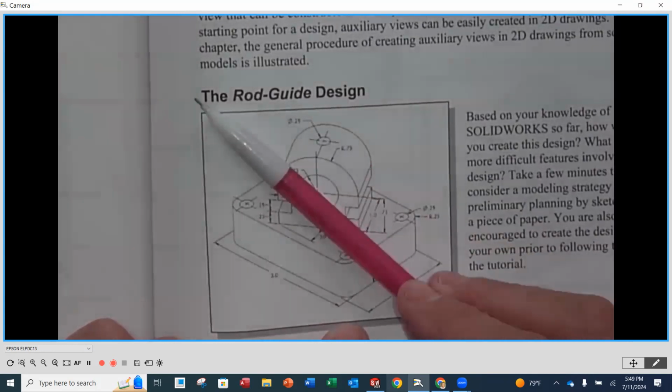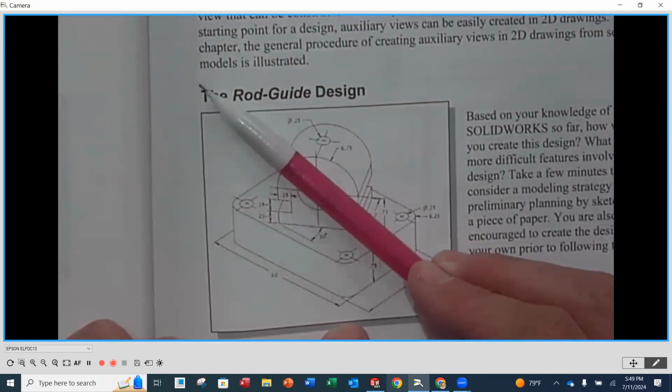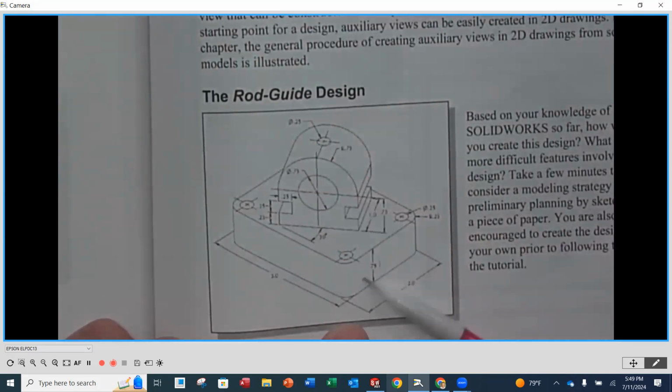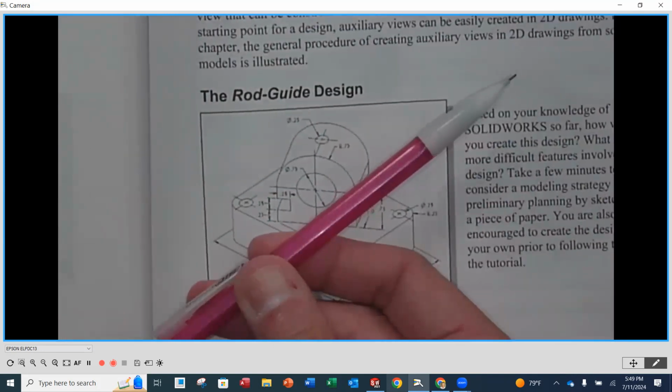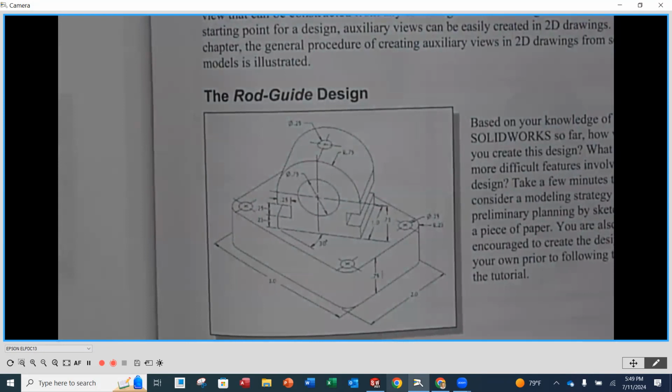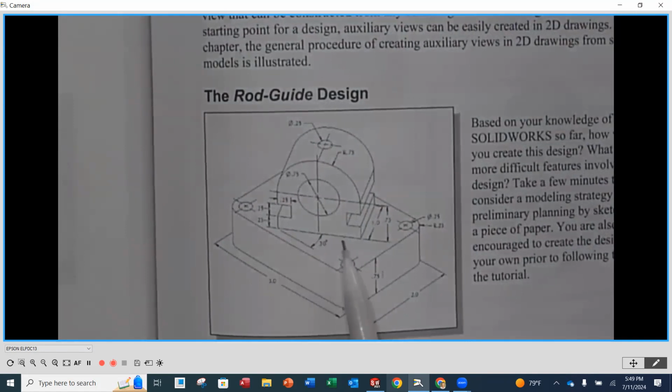So the principal view in our base is going to be the front view, the top view as it's sitting on, and then it's going to be the right side view. But those views or those planes are going to be mutually perpendicular 90 degrees to one another, okay? This is not at one of those principal views. This is 30 degrees off of, if you would, the front plane.